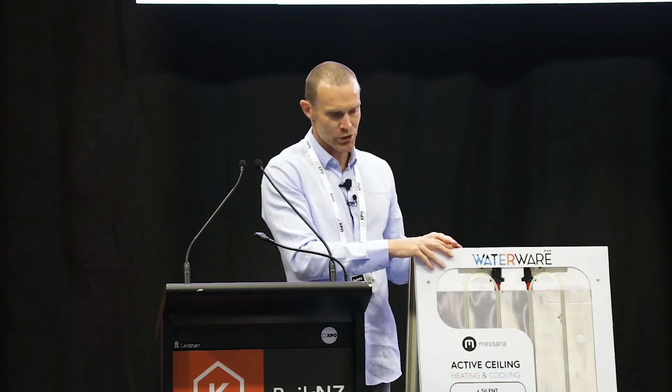And then you've got the ability to also split the panels. So if you've got a panel which is 2.4 meters long, you can cut it in the middle, split it apart by 200 mils to then mount lights in the center of your active zone if you like. When you come to do the installation, the panels basically get installed by the heat installer. He does his pipework connection, then your Sparky will come along, run the wires, and then your jib stopper comes along, plasters the ceiling as per normal. You can use any jib, any standard fibre board in the New Zealand market, so it doesn't matter whether it's 13 mil or 17 mil, aqua line, noise line, fire line, doesn't matter. So you jib the ceiling as per normal, and then that gives you a completely finished surface.